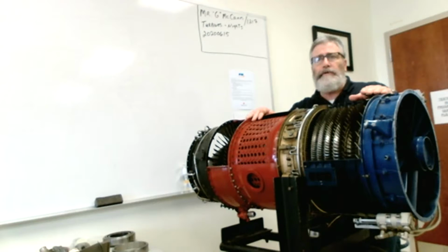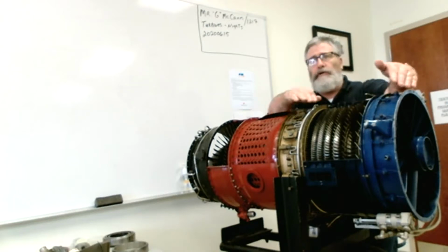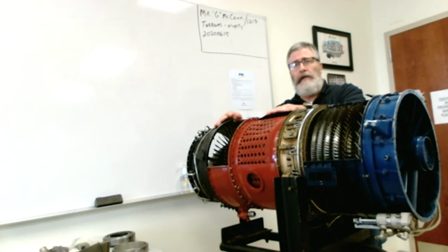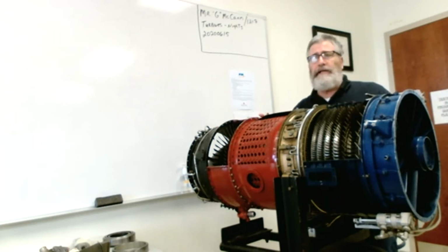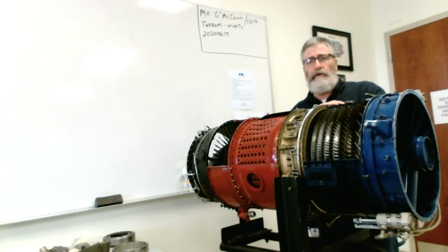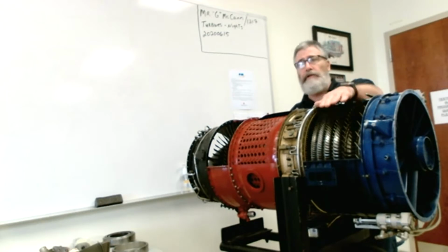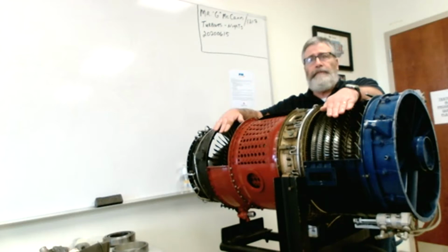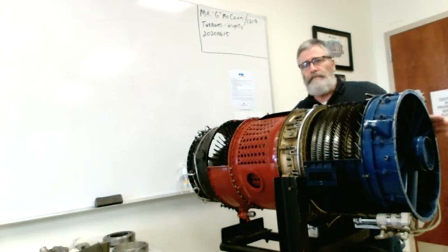The question comes up, what are the 2 basic sections of a turbine engine? Well, the 2 basic sections are the cold section and the hot section. Let's just stay with that. That'll be constant with any type of turbine. Another question comes up that says, what are the 3 main sections of a turbine engine? Even though there are other sections, the 3 main sections in the order that they operate are the compressor, the combustor, and the turbine. Now let's talk about the inlet for a minute.